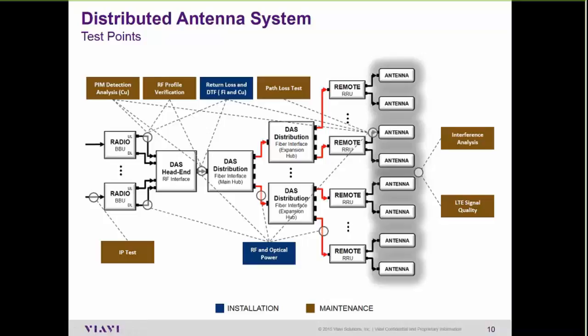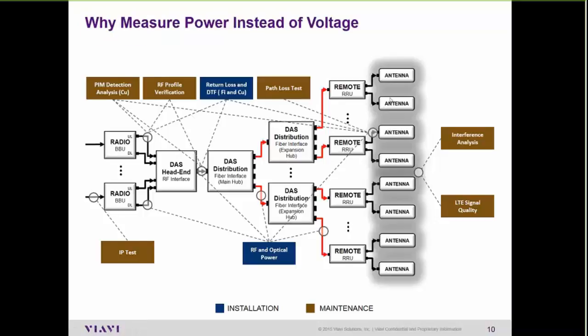And again, a plus or minus 1 dB can really affect coverage and interference and capacity in an area like an arena, public center, those types of things. So you get a lot more capacity, a lot better performance by having accurate power measurements. And a lot of the DAS systems themselves, just because you type in 30 dBm doesn't mean you're going to get a 1 watt output. It can definitely be off a little bit based on the type of unit or the calibration of that particular unit. So we've seen that in a lot of instances.